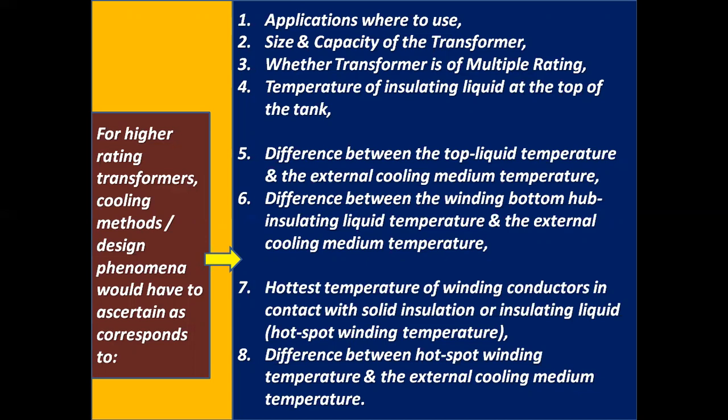Number four, temperature of insulating liquid at the top of the tank. Number five, difference between the top liquid temperature and the external cooling medium temperature. Number six, difference between the winding bottom hub insulating liquid temperature and the external cooling medium temperature.